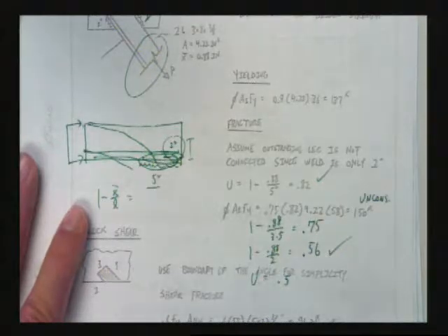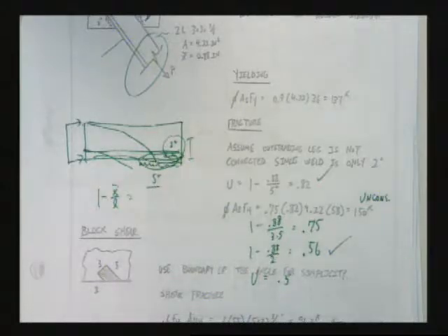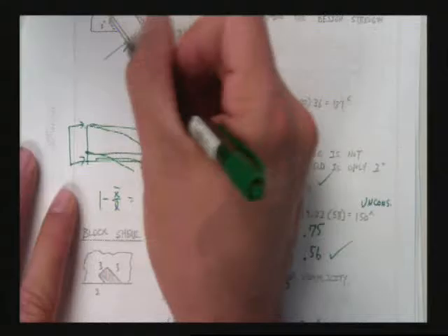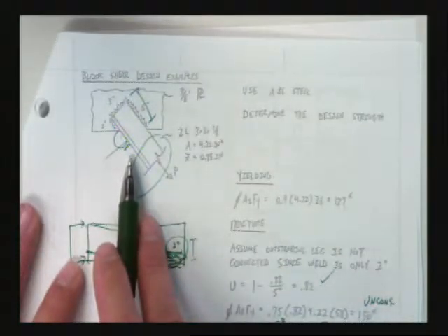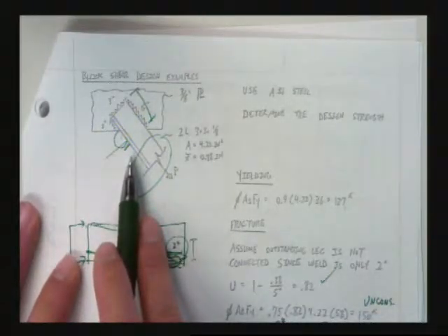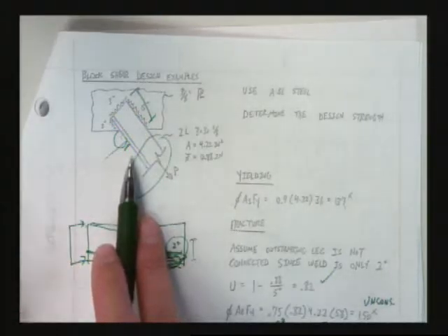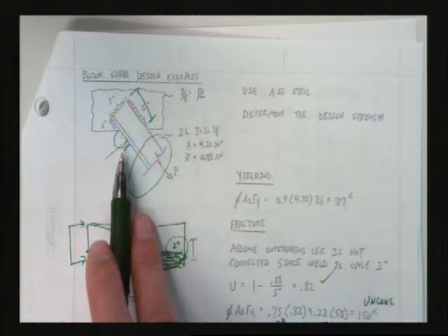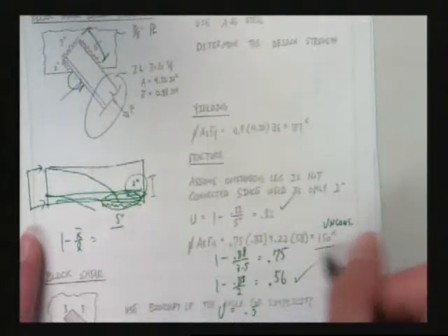And they're not. You wouldn't expect the load transfer to be the same on both sides, right? I wouldn't expect it to be. I wouldn't expect to assume that there's 5 more inches of weld over here where that load can leave my cross section when it's not actually there. You with me? So these are the types of things that you have to see and catch and say, you know what, this is a little bit unconservative.